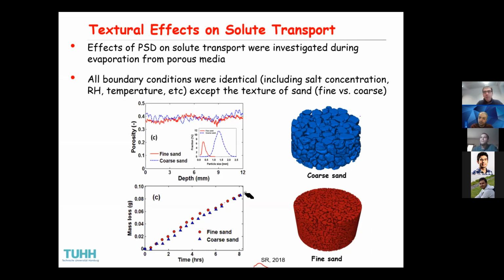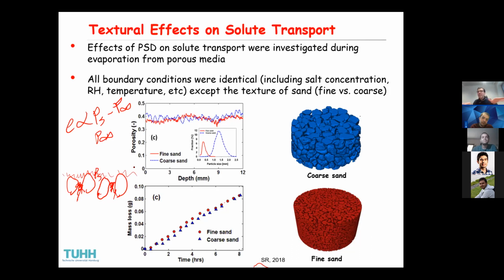Okay, yeah, that's a good question again. You are full of good questions, Marcel. So these are, let's say, some grains here, and this is the surface. Let's say you have some liquid here, some liquid here. Since the surface is partially wet, the evaporation rate is proportional to PS minus P infinity. Here is PS, the saturated vapor pressure, and this is P infinity. Since it is partially wet, the surface behaves as if it were fully saturated, because the vapor covers the entire surface. So PS doesn't change that much when the water content reduces.